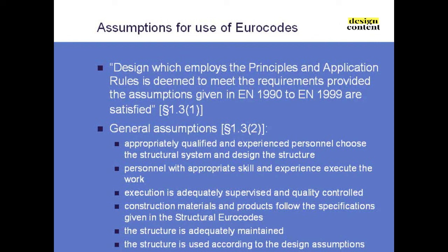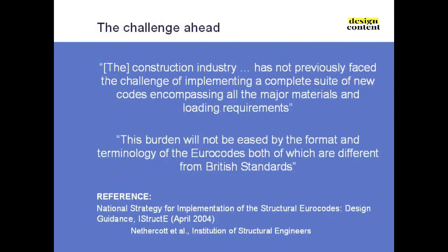I mentioned already that the construction materials and the products used follow the specifications in the Eurocodes. That's very important as well. I always point this one out to clients. The structure is adequately maintained. Just because the structure has a 120-year design life doesn't mean it will last 120 years without maintenance. It obviously doesn't. So clients have to maintain structures. And then again, very obviously, the design only works if the structure is used in accordance with the design assumptions. So it's no good designing a footbridge for footbridge loading and then trying to drive a lorry across it, because it isn't going to work.